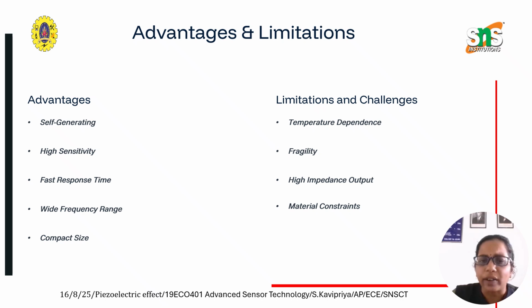And next, what are the advantages and limitations of the piezoelectric effect? First, it is self-generating, highly sensitive, and produces a very fast response time. The frequency range operated under this effect is wide and it is of very compact size. Limitations are that it is highly dependent on temperature and it is fragile, which means the crystalline lattice can easily break down. It also produces a high impedance output and has material constraints. The materials have to be chosen, natural or synthetic.